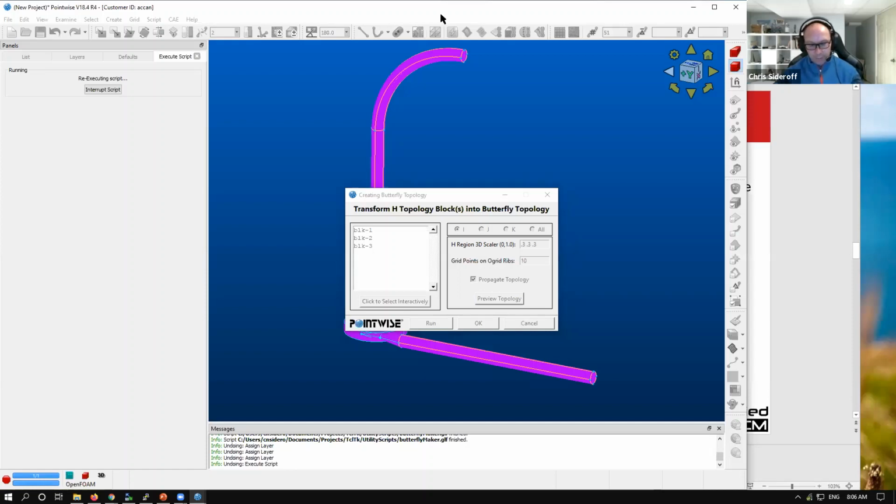So the first step I'm going to do is set the wall spacing explicitly. You have to use your structured meshes. Set the wall spacing explicitly, and then I'm setting it to the values that we're going to end up mating the unstructured mesh to.